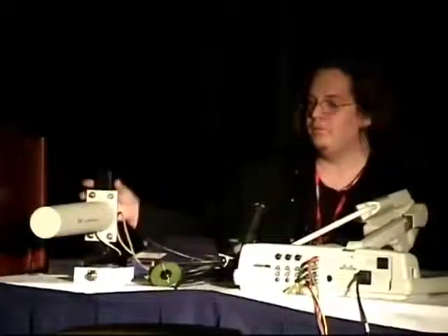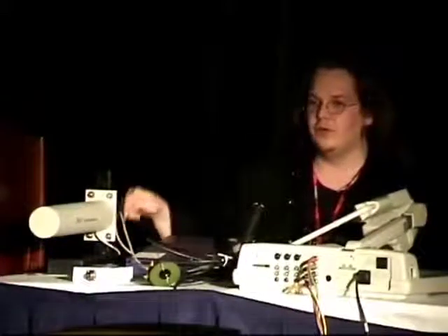So, other stuff we use. For comparison to the other figures we're using, this antenna would be a 14 dB gain for receive and transmit. Combined with the amp, it gives you an additional 14 dB on transmit and 30 dB on receive. So if you're trying to establish a long-range link, or if you're trying to see everything through your neighbors' houses, an amplifier could be a good investment.